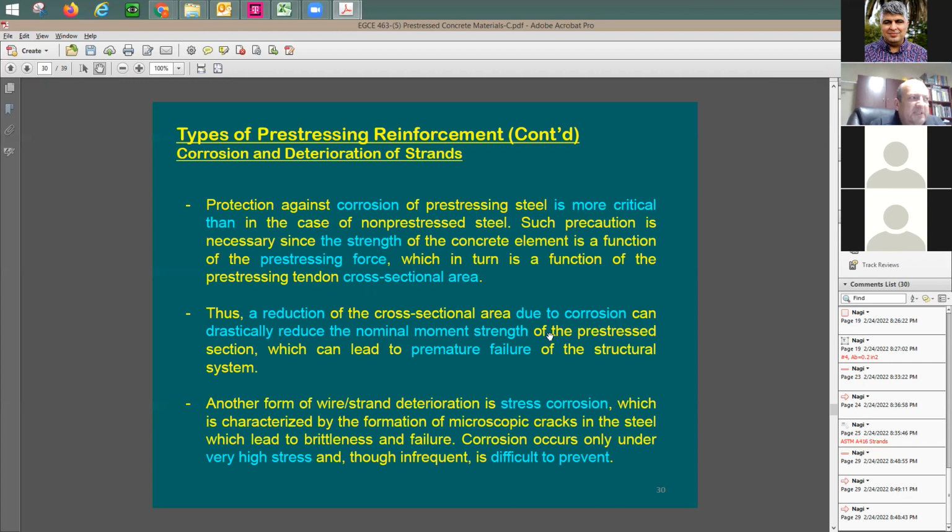Now the question is, what's the protection that you can do? A big issue here when it comes to protection is going to be in your design. You can design the structure to be free of cracks. And if you do this, there's not going to be any moisture intrusion or any chemical intrusion to the rebar. We do this a lot when it comes to water structures like tanks, water tanks. You do it this way.